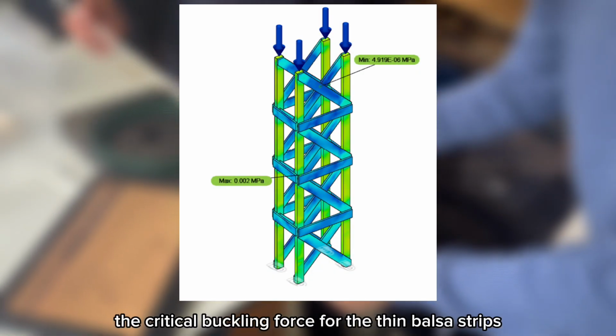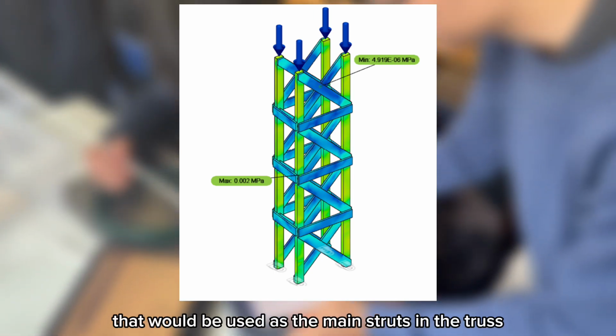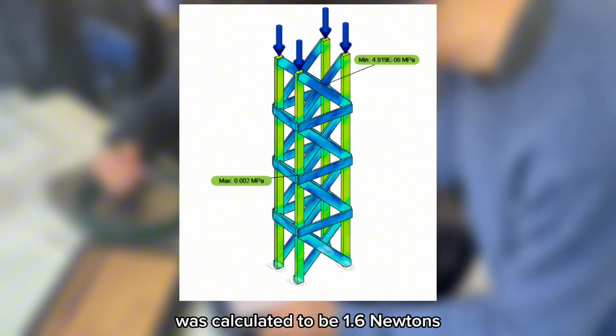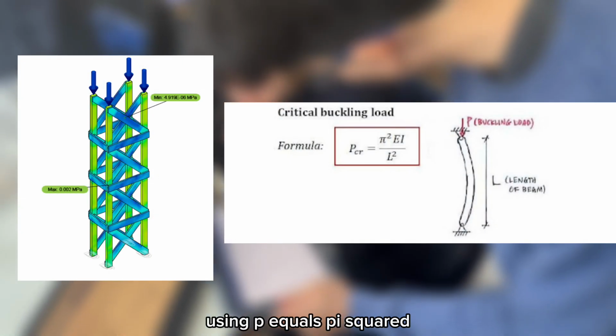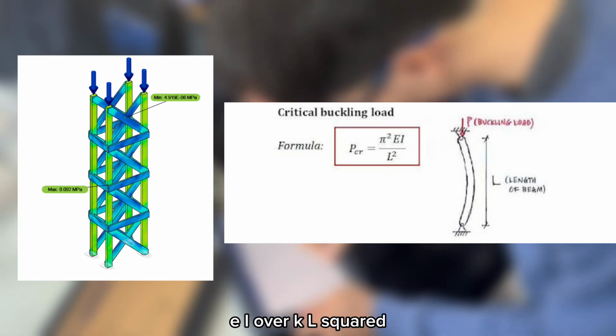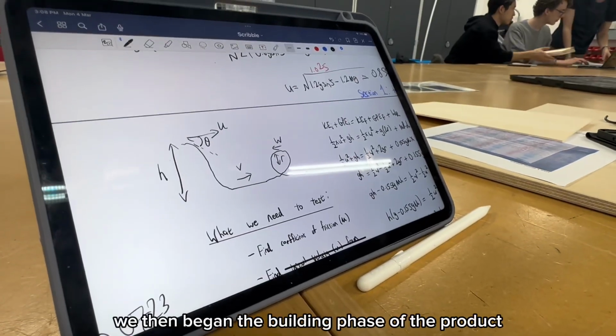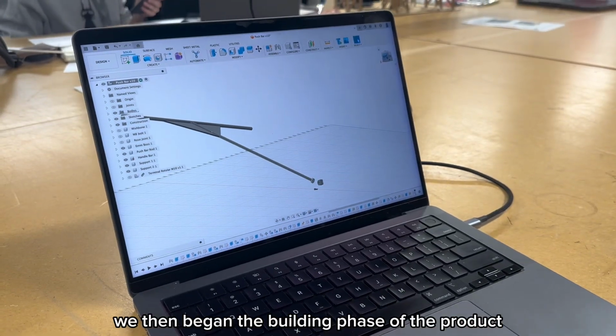Furthermore, the critical buckling force for the thin balsa strips that would be used as the main struts in the truss was calculated to be 1.6 newtons using P equals pi squared EI over KL squared. After figuring out the calculations and dimensions, we then began the building phase of the product.